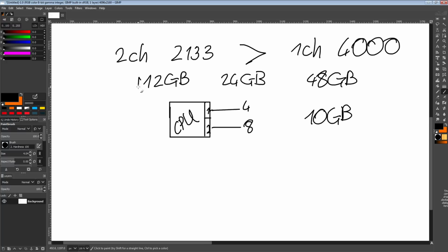But nonetheless, I would strongly recommend against running 12 gigs of memory on a dual channel CPU, like in an asymmetrical 4+8 configuration, because essentially you're going to end up with your memory performance randomly tanking within various workloads, and it could lead to stutter and all kinds of other hard to trace issues. It'll only show up once you start using enough of the memory that the memory controller can no longer evenly share the data across both channels, and then you end up with stuff that takes twice as long to access because it's stuck on one channel, not on both anymore.